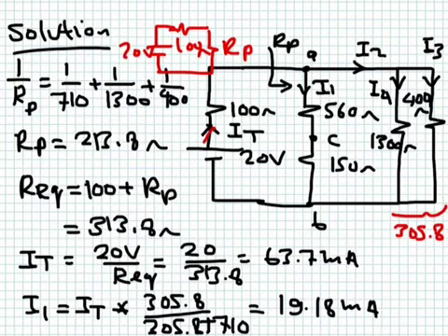The current flowing here, I total, is the same current flowing here, it is the same branch. So this current I total will flow this way, and then it will split into I1 and I2, and then I2 will split into I3 and I4. Okay, so now what remains to calculate the currents is to do a number of current divisions.